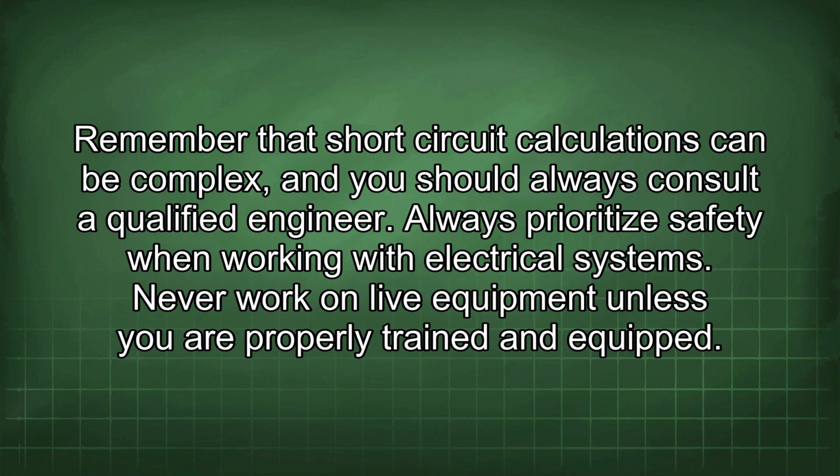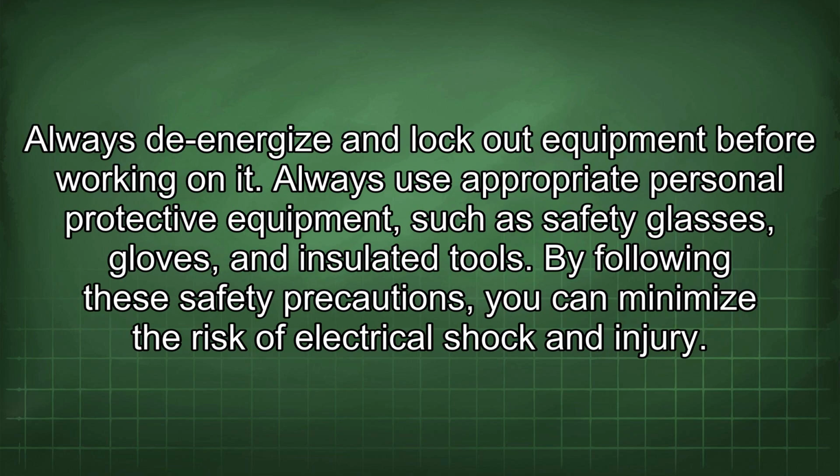Remember that short circuit calculations can be complex, and you should always consult a qualified engineer. Always prioritize safety when working with electrical systems. Never work on live equipment unless you're properly trained and equipped. Always de-energize and lock out equipment before working on it. Always use appropriate personal protective equipment, such as safety glasses, gloves, and insulated tools. By following these safety precautions, you can minimize the risk of electrical shock and injury.